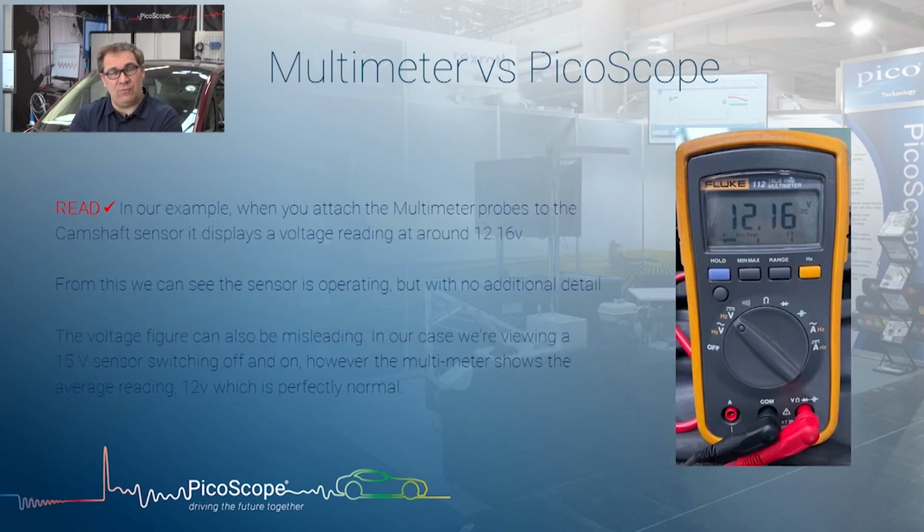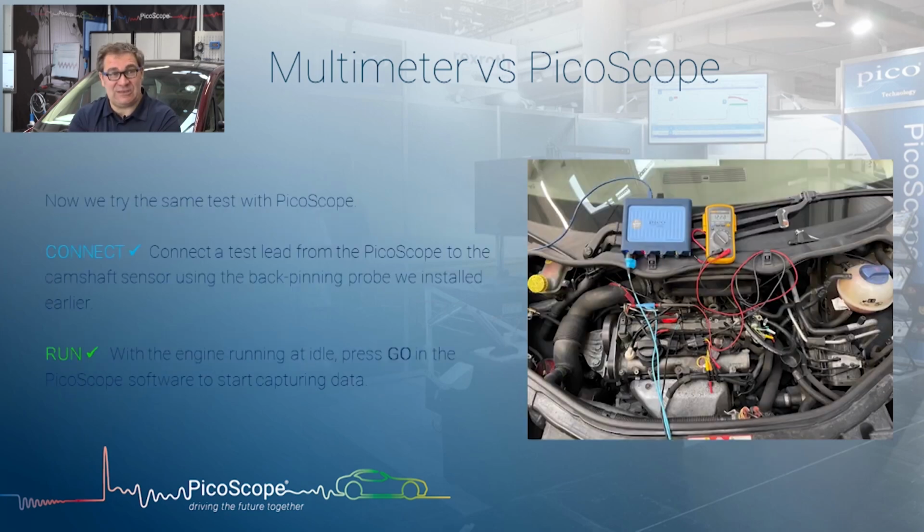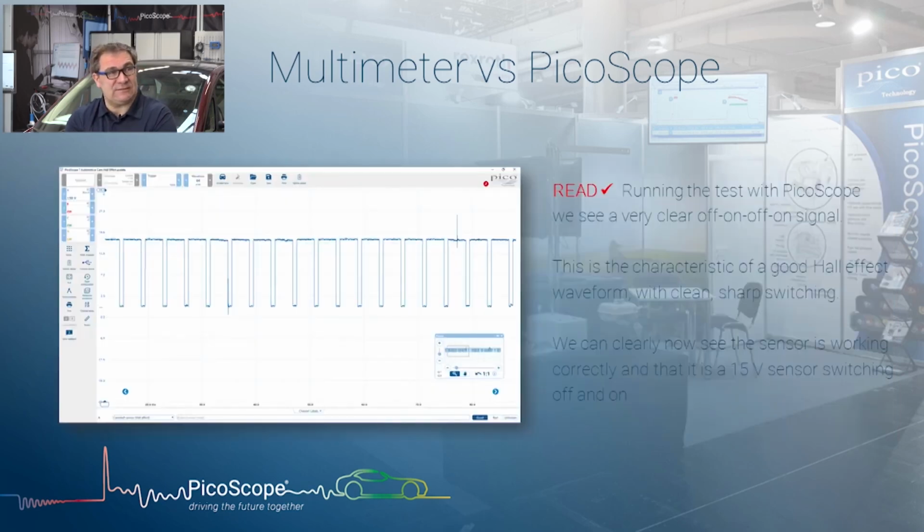We've got 12.16 volts. So if you have a look at that very quickly, you'd think, oh, well, that's a 12-volt sensor. Actually, it's not quite as simple as that, and I'll just show you what we see when we look at PicoScope. So connecting in the same way, as Phil will do here, we literally piggyback through that back pinning probe with a multimeter and PicoScope. And again, we're running with the engine on idle. All we have to do is just tell the software, so press go on the software and that will start to capture our data.